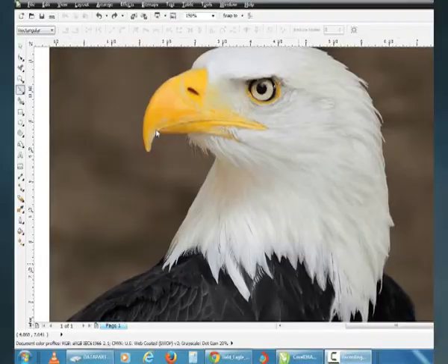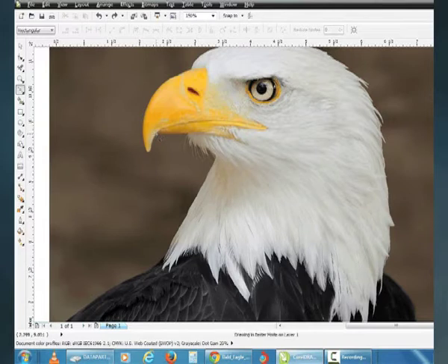In fact, after the completion of objects or tracing by this tool, you still have access and freedom of doing any kind of editing in it. To use this tool, first you need to select it. Before starting, bring any logo or scanned drawing. Click your mouse first button on the object you want to trace or make as shown in the picture.